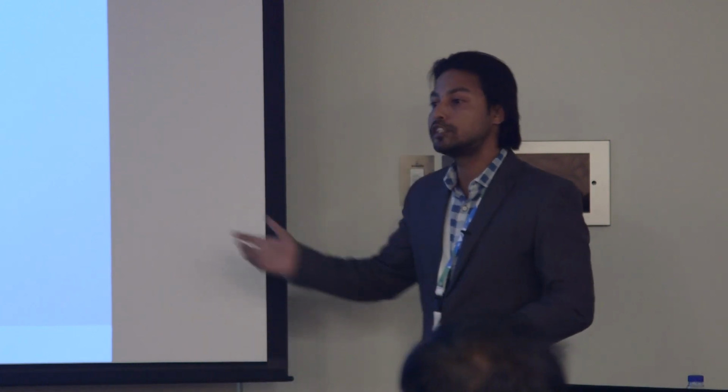One of the tools that I would really like to highlight here is the Rebuild tool. What it does is, if you have an AutoCAD file which you underlay in Revit and then start tracing all the walls and everything, this tool reads all the data from your AutoCAD files in terms of your layering. Let's say you have double lines or single lines, whatever it is. It reads the data, you have certain options to format it, and then it generates the walls for you. So just by reading the lines, it creates the walls.